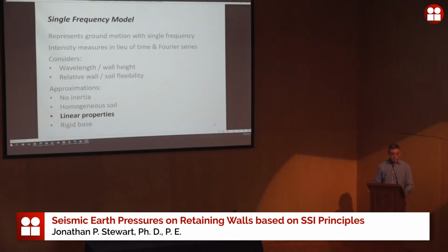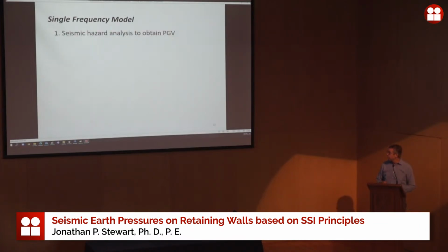The stiffness goes down. That makes the stiffness intensity smaller. These counteract each other. Not perfectly, but when you actually run through different cases, you find that the change you get by going to nonlinear is pretty small, and it makes the analysis a lot more complicated to deal with. So this is why we went with linear in the interest of simplicity, but also because it actually works pretty well due to these counteracting effects.